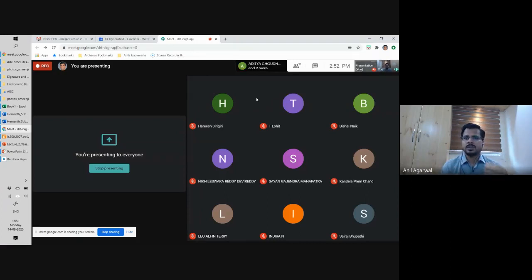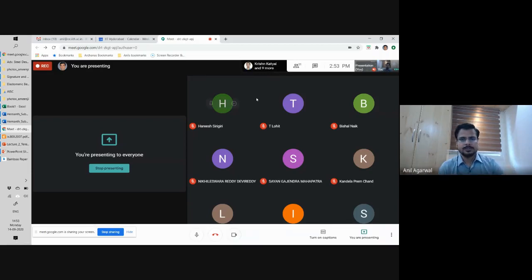We can give different names, but if you look at the material level, it is mostly either yielding or rupture, or at the member level, it is mostly buckling. Okay, or at the system level, it could be buckling. So these are the 2-3 primary types of limits that govern the safety of the structure. The second one, the strength limit state, is generally something to do with the safety of the structure. The first one is not so much to do with the safety, but more of the comfort. Serviceability limit state is more on the comfort side of it, and this is more on the safety side of it. Okay.